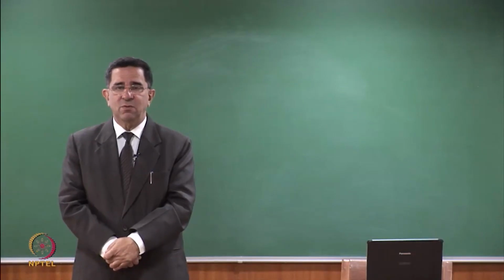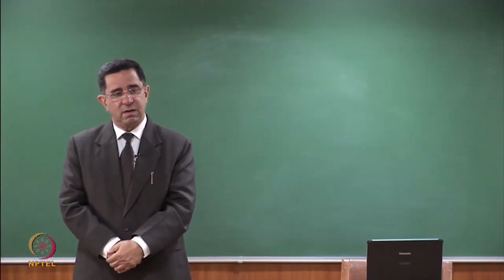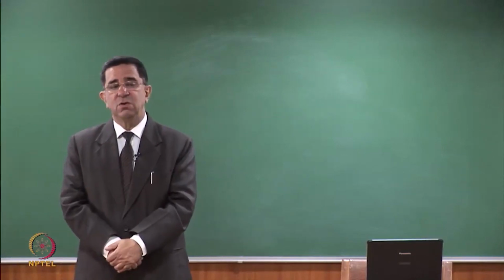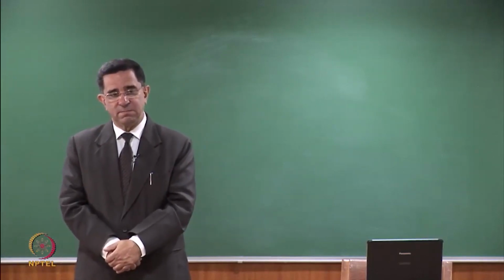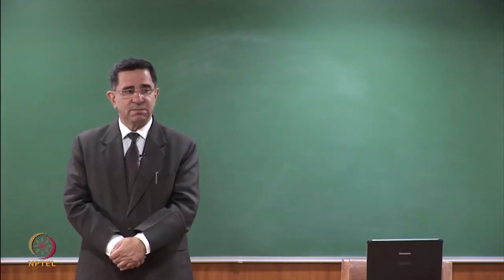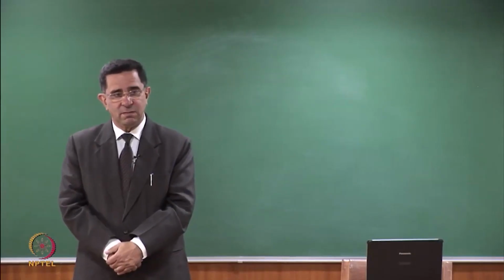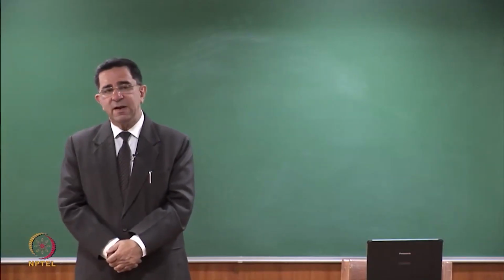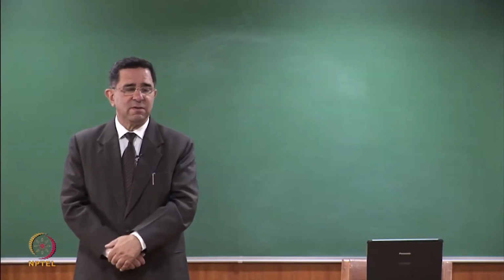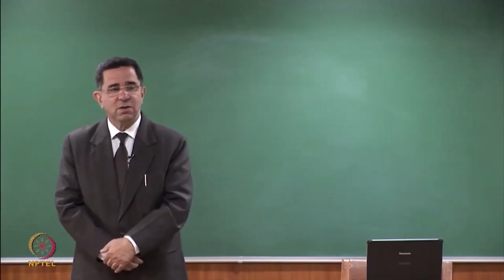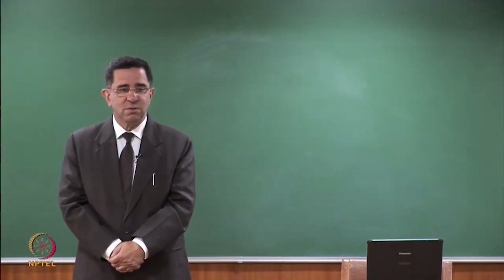Other than grain size, how would you like to classify? How would you like to go about classifying ash in terms of geotechnical or geoenvironmental properties? Specific gravity is important, somebody suggested. When you start identifying soils, what are the two most important tests that you do? If I bring soil from a particular site and give it to you, what are the two sets of tests that you do to be able to understand the soil?